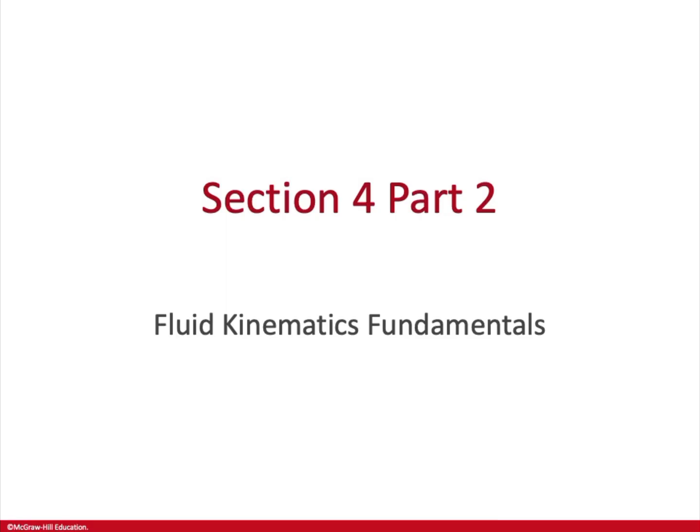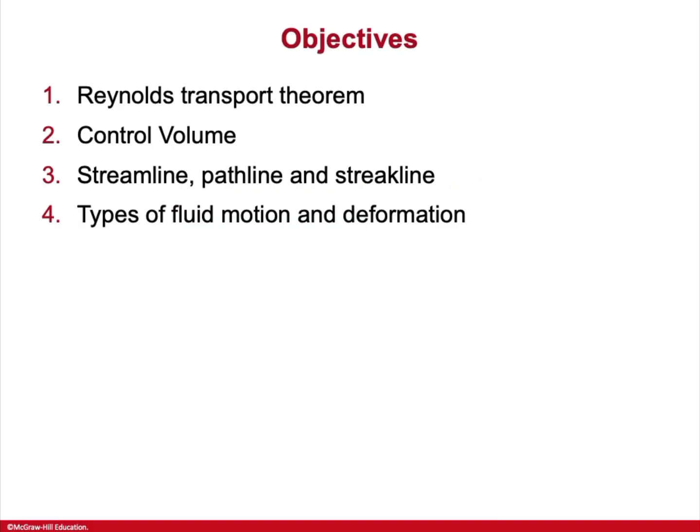Okay, so now we'll move on to the second part of fluid kinematic fundamentals. The two things we'll primarily focus on are the control volume concept and the Reynolds transport theorem, that is, the relationship to connect the Lagrangian and Eulerian descriptions if you are doing an integral analysis.